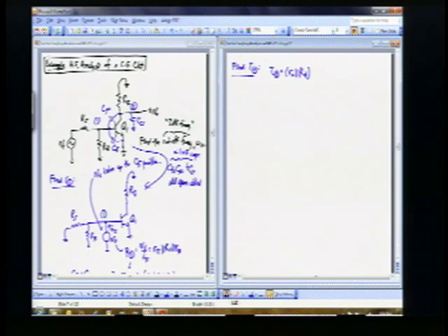I don't know why I'm doing that today, just because I haven't told you what RC is. It could be like a mega ohm or so, in which case I have to take into account R naught. But usually you'll neglect the R naught. So the tau just becomes this R naught parallel with RC and times the CCS. Okay? And so that now is our third time constant.